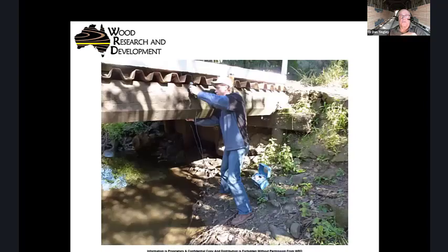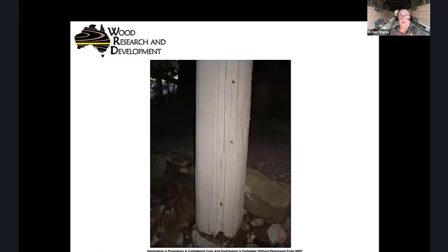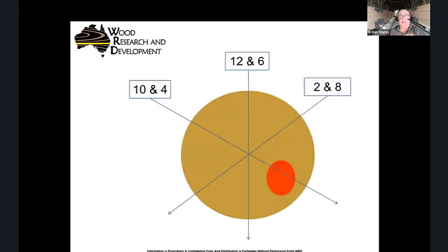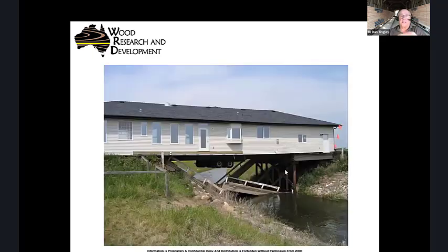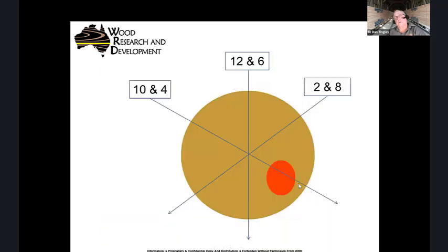When we can use non-destructive testing like this one to find bad actors, calibrate these bad actors, find these guys before they find us, so that they don't end up like this. This was outside of Brisbane. We're going to put a new precast concrete on the old timber piles. We just drilled holes in them and found nothing going on, so we let them go.